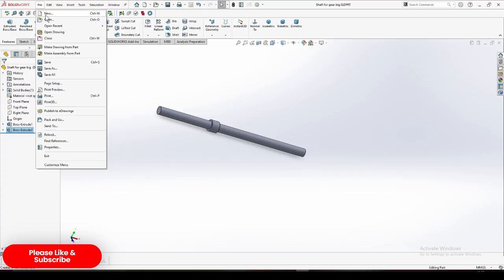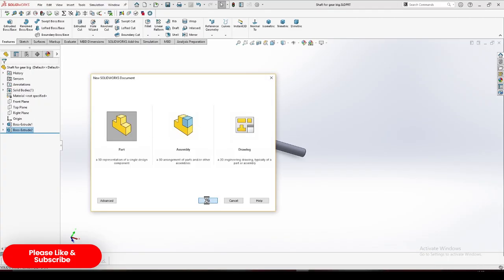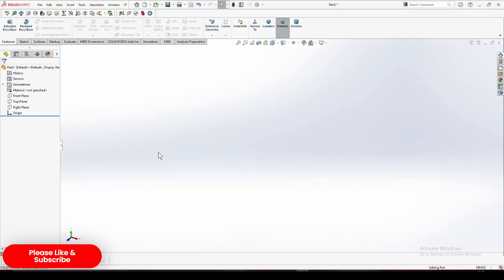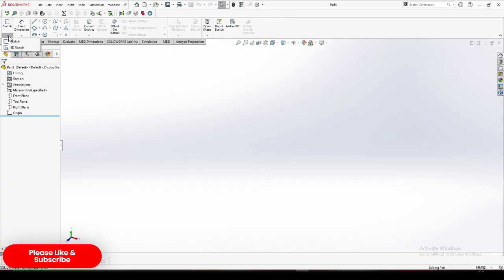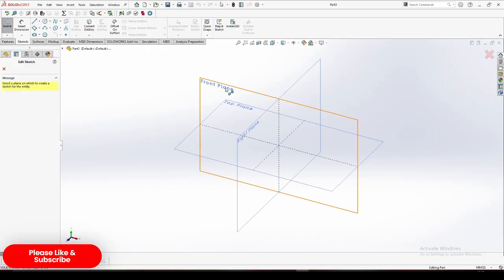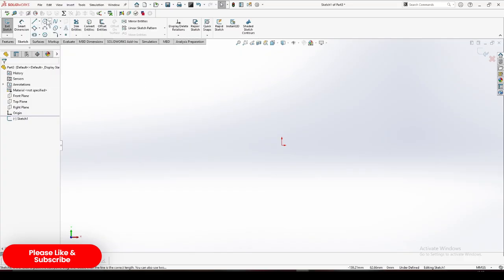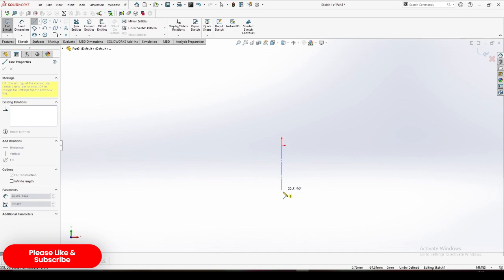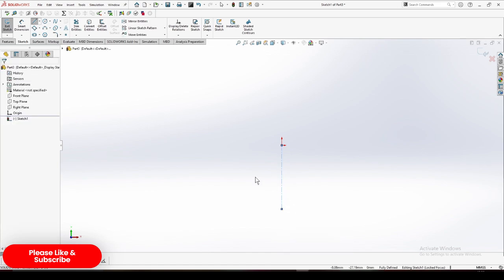This is valve retainers. So in this we will create two sketches, and we will use the command revolve boss base to make the valve retainers. So let's see, go to sketch and select front plane. Go to center line. So here we will draw one center line for our reference purpose. It should be vertical. Remember that one. Select. Now we are going to draw our sketch.